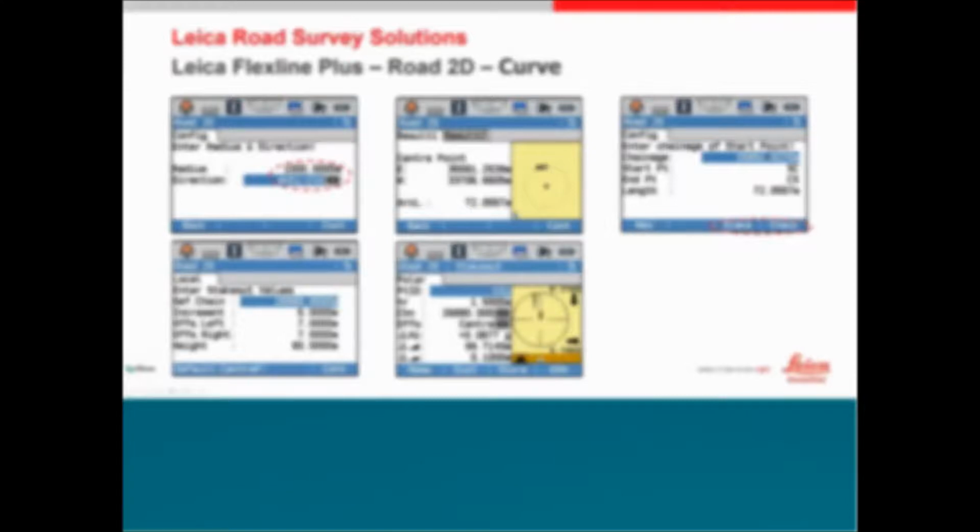So you choose which one you want to use and put in the chainage again. After that, like I say, you must be within the elements. Then you can set the bull's eye on, and you can see whether you are at the chainage and offset that you want or not.